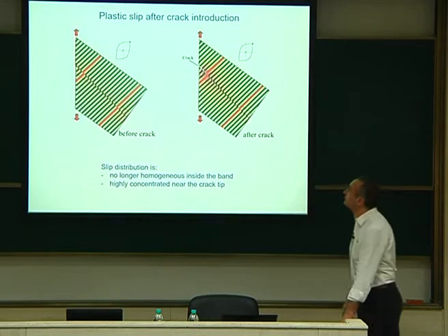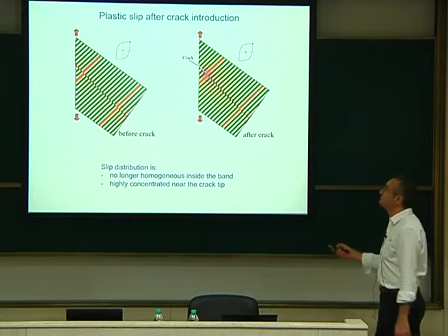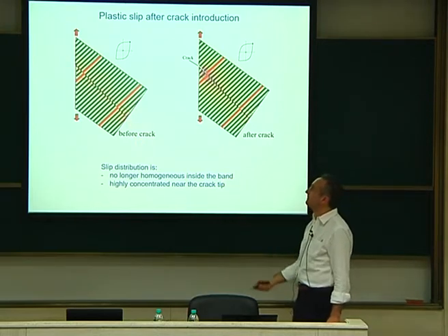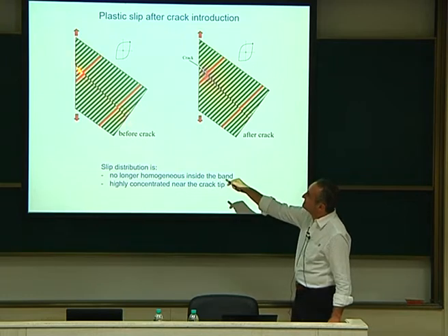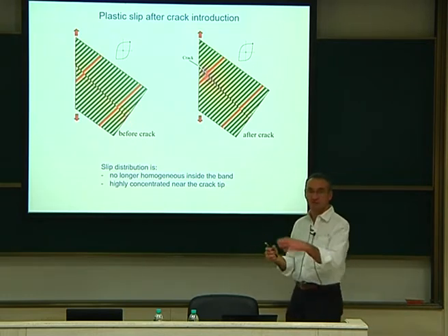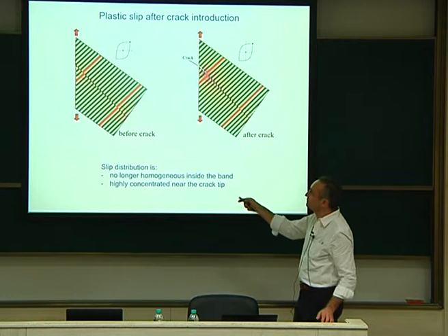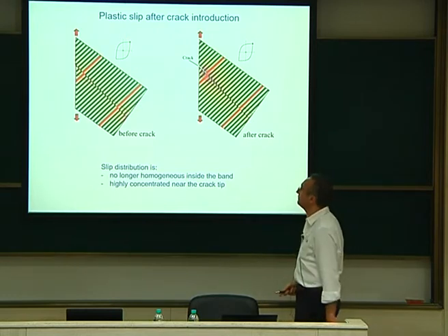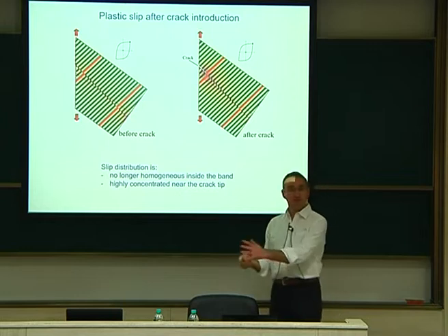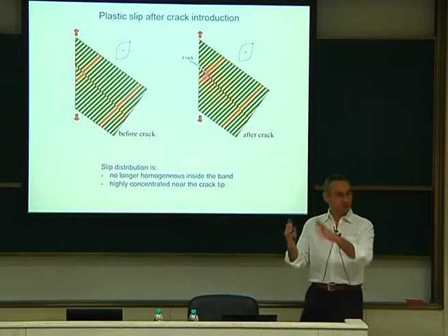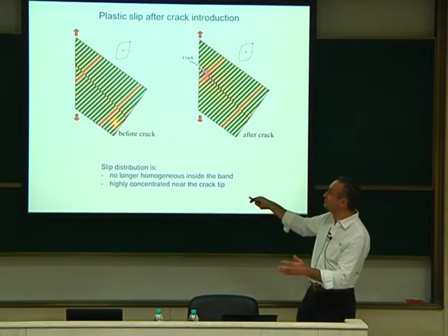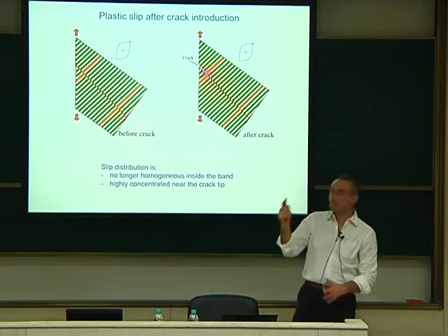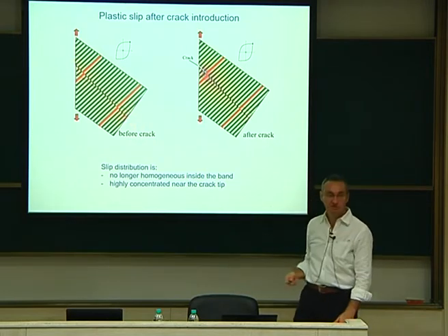So now if we look inside the simulation, this is the simulation as I showed yesterday. You can see the persistent band at that place. This is where the plasticity is localized. Again, we put some zebra to see where it is localized, to visualize. It's better to see how it's deforming. This is the case where everything is the most deformed. At that stage, the crack was not introduced, so this is what I showed yesterday. You have your persistent band, and you can see that it is sheared everywhere, more or less. You see the band shear the matrix everywhere. At that place or that place, the deformation is more or less the same.